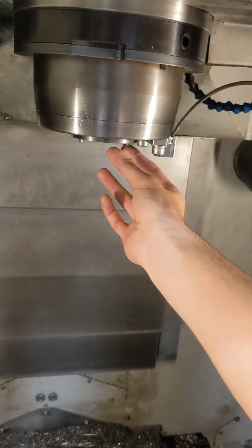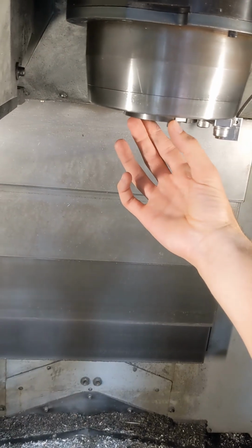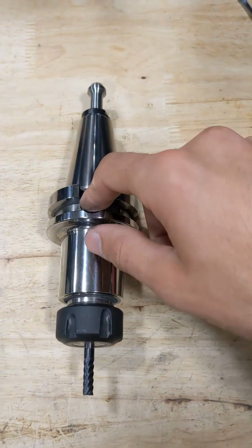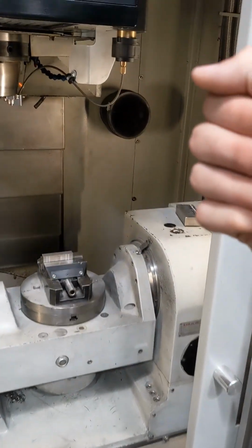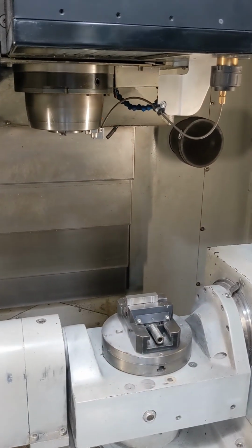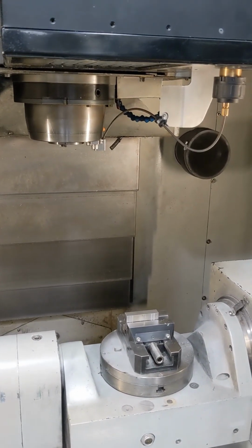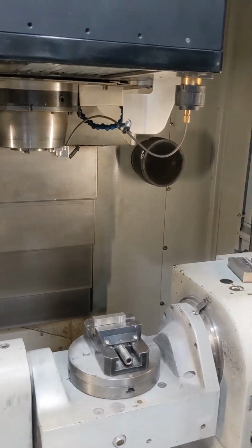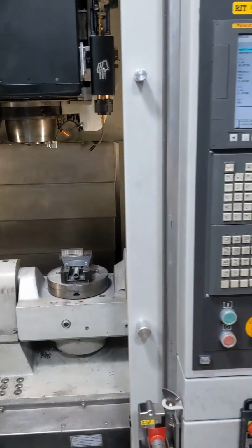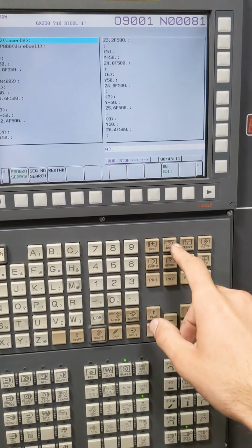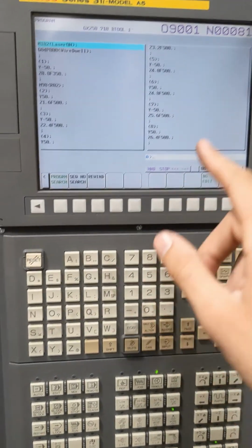So you just have to make sure those little bosses are aligned with the cutouts on your tool. And then once the tool is seated properly, let go of the button, and then it'll be secure in the tool changer, or in the spindle. So once you do that, it's crucial immediately after that to measure the tool height, and that'll be shown in another video.